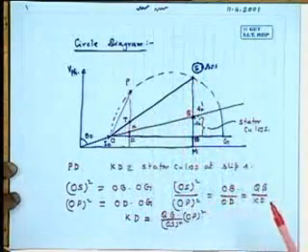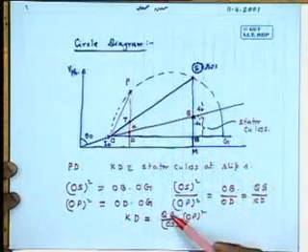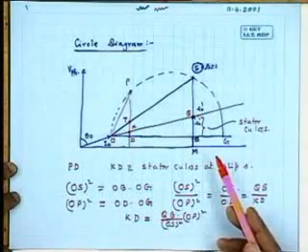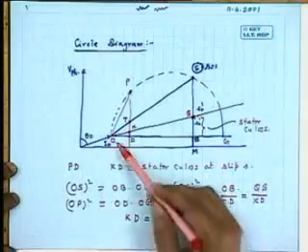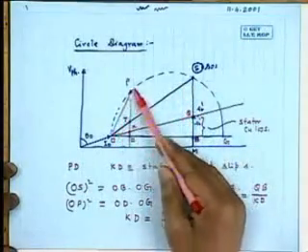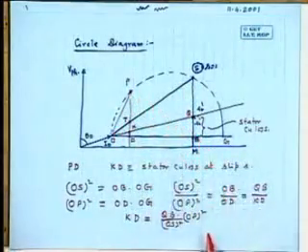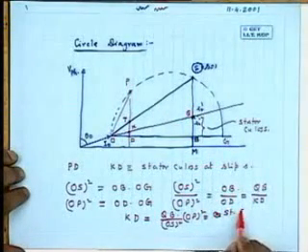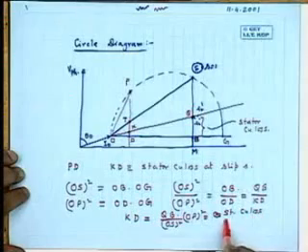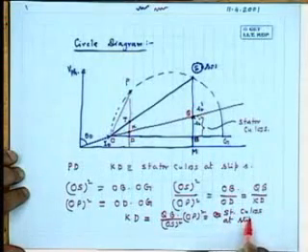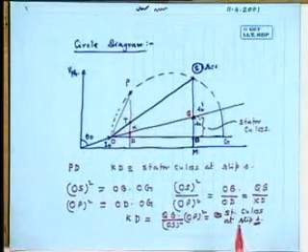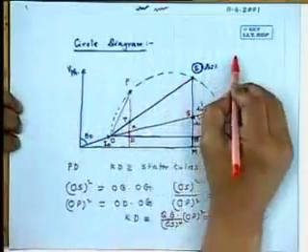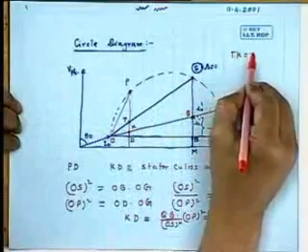OS is the current value at that slip. So that power divided by OS square will give you basically R1. And this multiplied by OP square, the current square at slip S, is therefore nothing but the stator copper loss at slip S. Similarly, you can show that the length TK will represent the rotor copper loss.